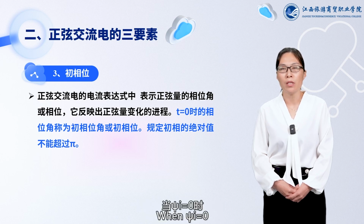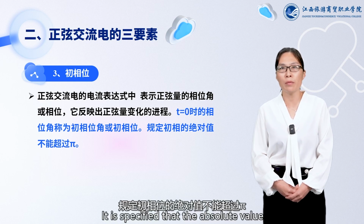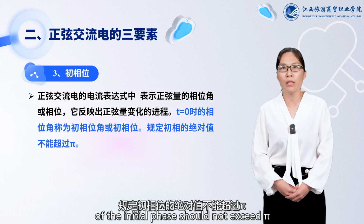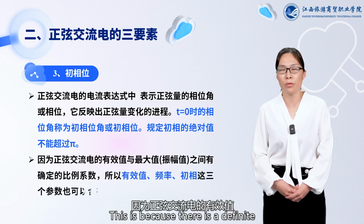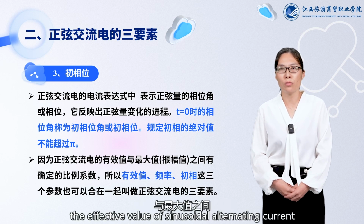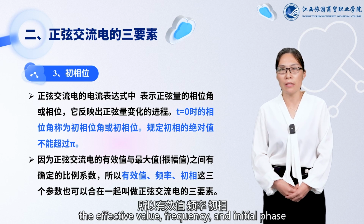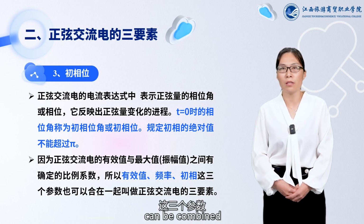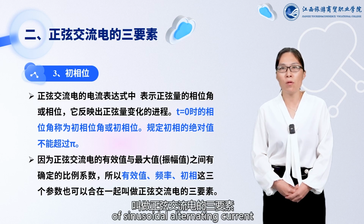When phi i equals 0, the initial value is 0. It is specified that the absolute value of the initial phase should not exceed pi. This is because there is a defined proportional coefficient between the effective value of sinusoidal alternating current and its maximum value. Therefore, the effective value, frequency, and initial phase can be combined and referred to as the three elements of sinusoidal alternating current.